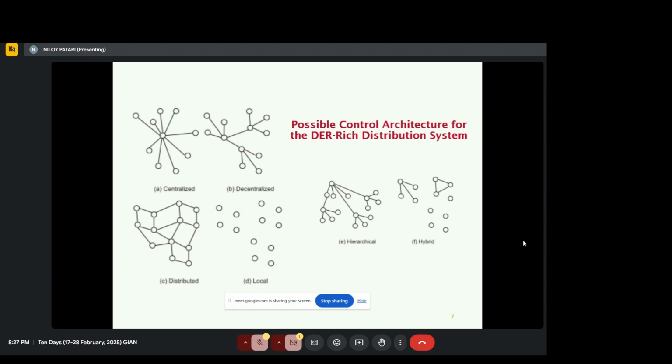In the ADMS, there is an optimization solver, and they compute decision variables. Decision variables mean which caps should be switched on or not, what should be the set point of the battery, and all of that. And then they send those set points back to the agents.